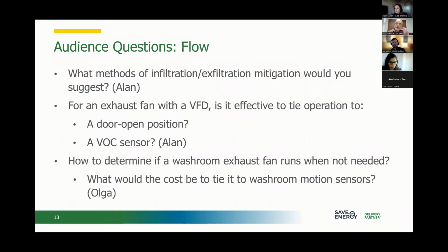And I think one of the suggestions that jumps out from what you're saying is that it needs another duct coming into this with another damper on it. At the same time that the VOC sensor is triggering that, oh, we've got to start evacuating, a damper has to open up into a ductwork at the same time that a fan speeds up. And then that way the door is kind of a non-issue with this. Something like that, right? All right.